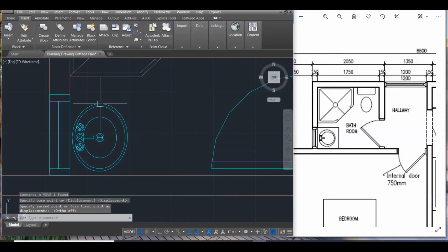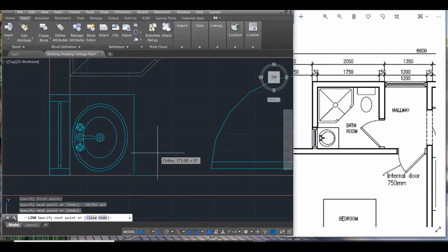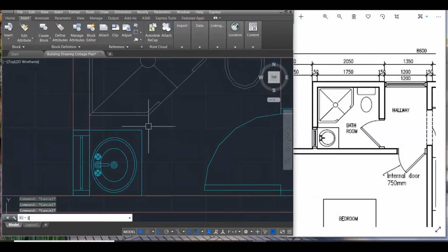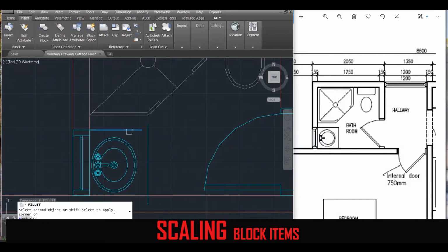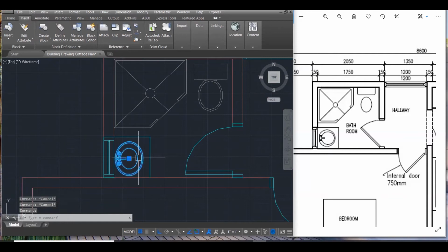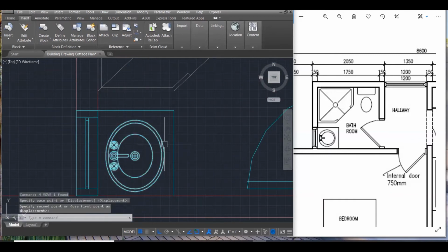And 2, not everything that comes out of the block menu comes right into your screen at the exact point that you want it. Perhaps this is a setting that I need to turn on or turn off. But it is always important to know how to scale and to know where your items appear on the screen when they're coming out of the block menu, so that you can insert them into the correct spot. All right. So I've shown you just in this room about 3 different methods of scaling that I use to get my things into position.